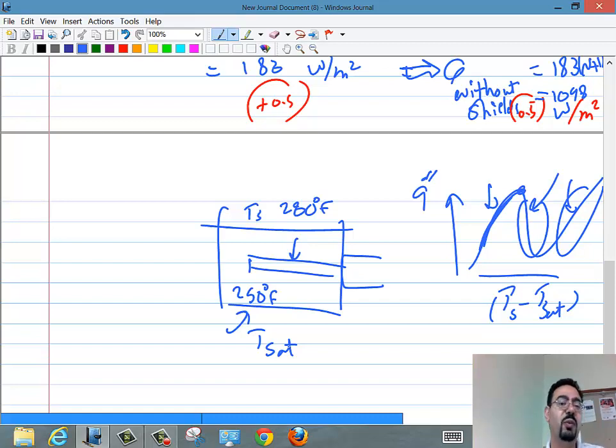When you start the boiling, this wasn't the case. The water was not at 250 Fahrenheit, probably it was at 70 degrees Fahrenheit. And the heating element initially wouldn't make any bubbles because it couldn't sustain a temperature higher than T saturation, because it was surrounded by very cold water. And it eventually started heating the water around it, and because it really just gives you Q, the resistance inside does not control the temperature.